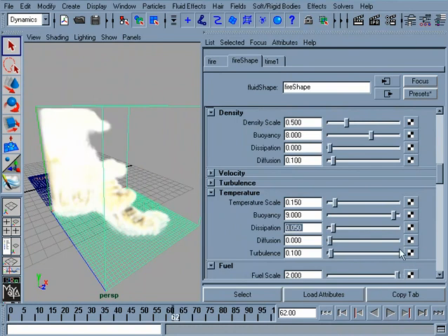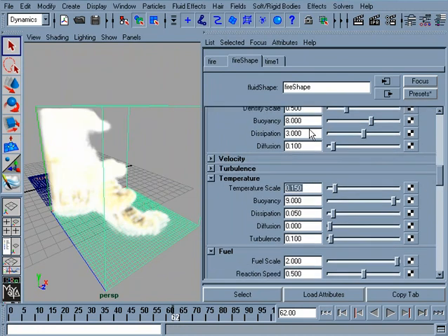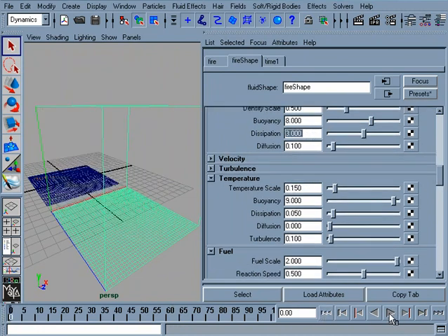Okay, so now playing this through, you can see, yes, the flames are definitely a lighter color, but now the flames are even worse than they were. I mean, now I've got just this inferno going on within my scene. So what I probably need to do is take this density, which I believe I set to 0, which it probably doesn't need to be that low. That density dissipation is what's causing this to last forever and ever. So let's try something like 3 as the density dissipation, and let's see what that does for us.